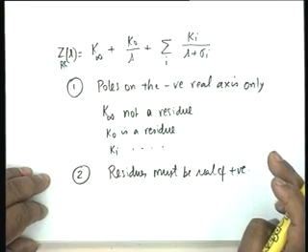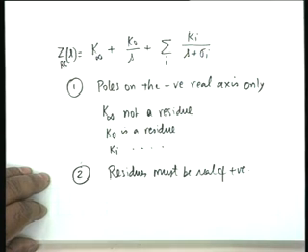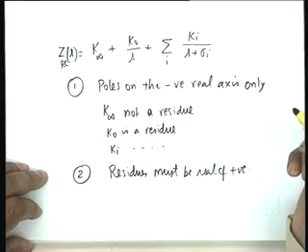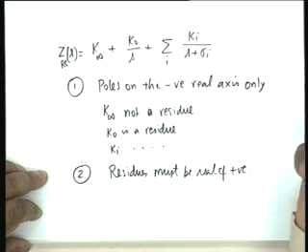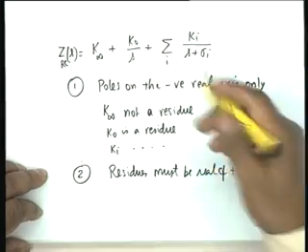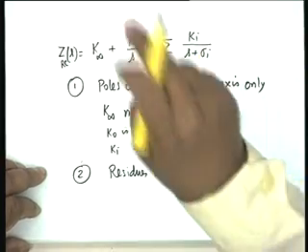Any questions so far? Now, I could do this for an RC admittance also. I am taking a slight detour to bring another point. I have concluded that poles are on the negative real axis. What about the zeros? Can the zeros be anywhere else? To come to a conclusion about the zeros of ZRC, we look at the poles of YRC. Now, what would be the most general form for a YRC?